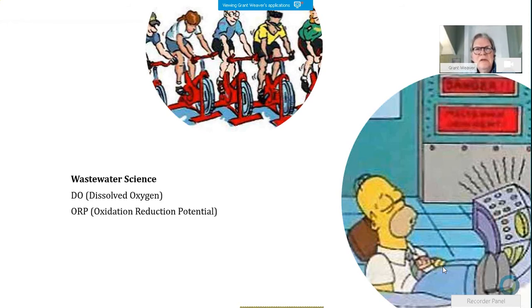If there's no DO available, or if they're working to breathe the oxygen that's combined, even if the DO is available, the ORP will go into negative numbers. Dissolved oxygen probe stops, obviously, when the dissolved oxygen is 0. The ORP tells you how anaerobic, how strongly septic the water is. Nice tool. It's got its downsides, the reproducibility.